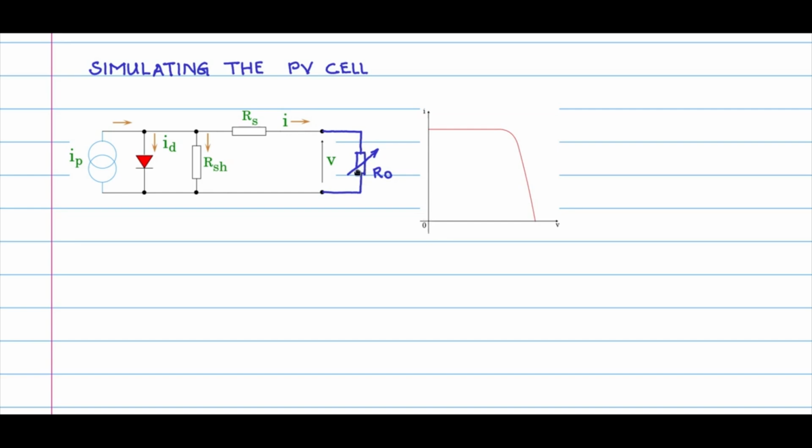And when you try to increase R0 to a larger value, this I into this R0 value at that point in time would give you a voltage which would sweep the x-axis. So basically we would have an x-axis sweep voltage value, and when you measure the current, you would get the various points which would represent the IV curve.